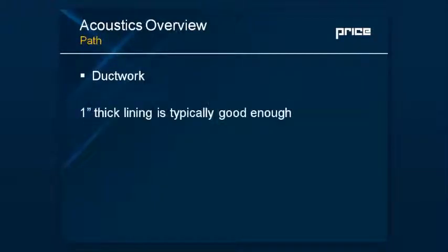In terms of ductwork then, some conclusions we can draw. 1-inch lining is typically good enough. Again, the 2-inch versus 1-inch didn't have a huge difference in terms of insertion loss performance, especially in the high frequencies. They were identical. In the low frequencies, they were very close.